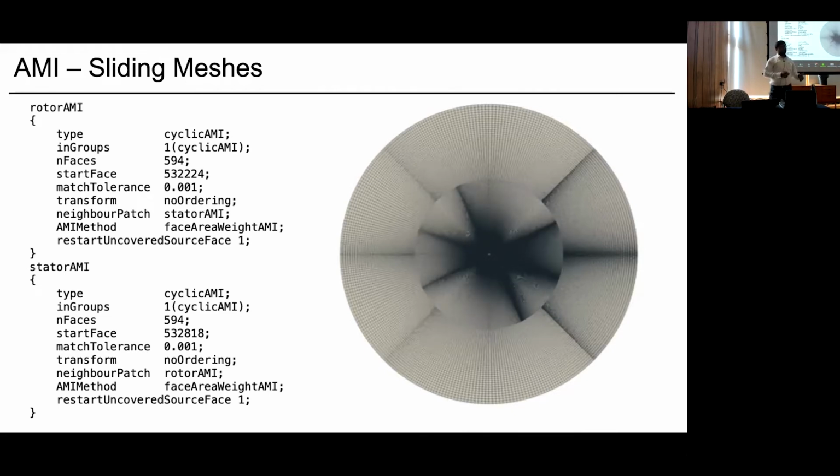So one approach is that when you mesh it, you define the interfaces, that means the outer patch of the inner mesh to be AMI, arbitrary mesh interface, and the inner patch of the outer body also as AMI. AMI1, AMI2, and then you apply this condition, which is called cyclic AMI condition, and one has to be the master mesh, another has to be the slave.